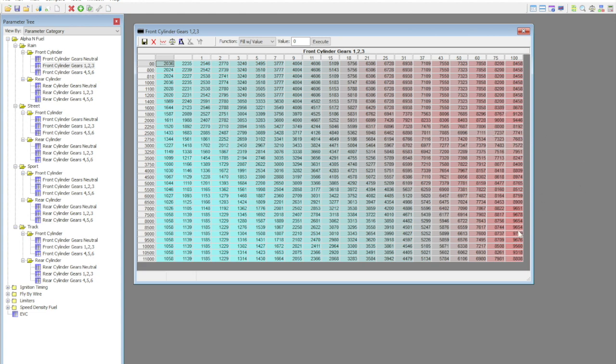These numbers represent injector on time. It's kind of an arbitrary factor. You can ignore what it represents. You just know that the larger number is more fuel output, lower number, smaller fuel output. So as throttle goes up, so does fueling.